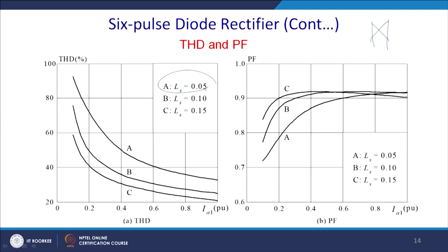and for this reason you can see that this is the graph for quite low source inductance. So, this is the curve while increasing the load, and this is the curve for Ls equal to 0.1 for increasing this load. For having a considerable amount of source inductance, you can see that the THD comes out to be close to 5% here, and is quite acceptable.